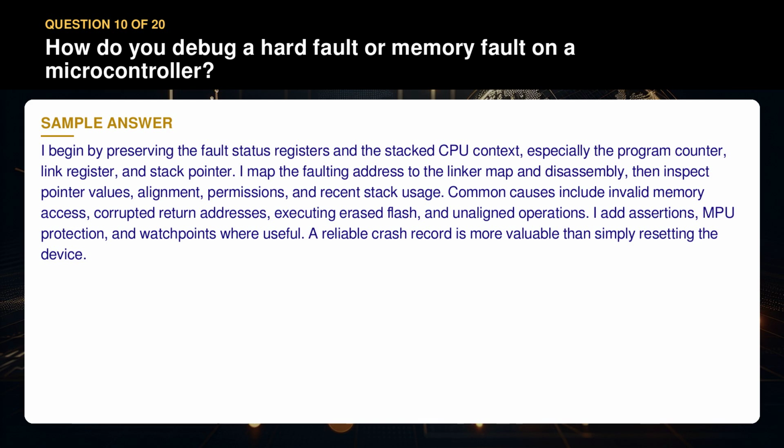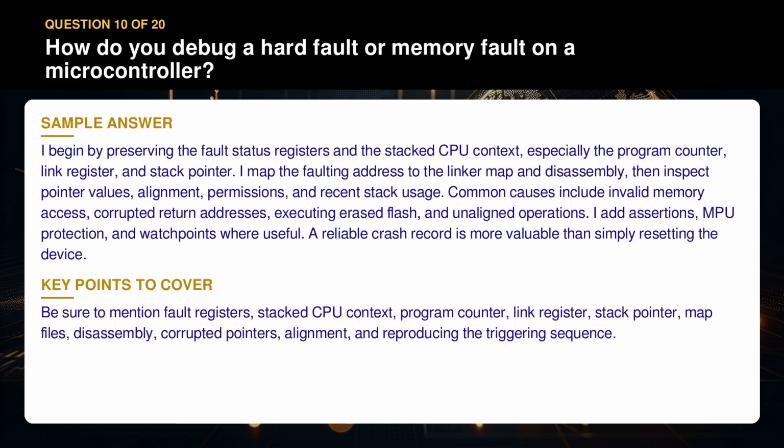I add assertions, MPU protection, and watch points where useful. A reliable crash record is more valuable than simply resetting the device. Be sure to mention fault registers, stacked CPU context, program counter, link register, stack pointer, map files, disassembly, corrupted pointers, alignment, and reproducing the triggering sequence.